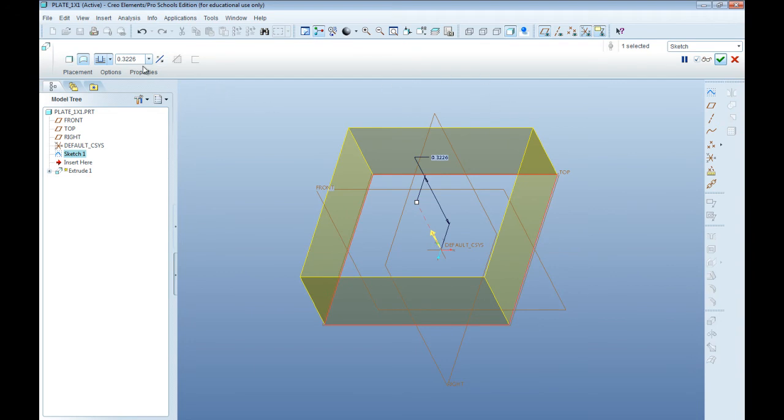The dimension we just input is also saved in this drop-down box, which contains a list of other recommended sizes, none of which are really recommended for us. But if we want to go back to a dimension we don't remember exactly, we can always see underneath here, and it's usually saved. So we'll click solid, and we'll click the check mark indicating that we're done creating the feature.